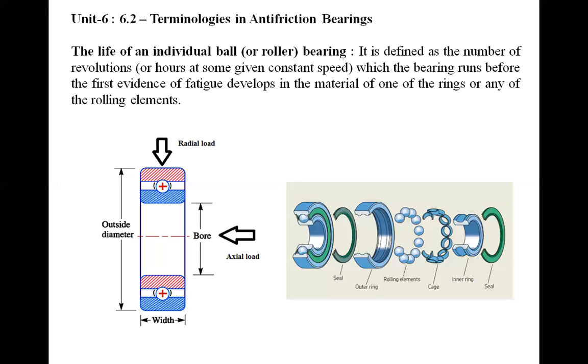That means a compression-release type of loading happens on the ball or roller. Because of such repeated loading on any component, it is subjected to cracks, and that property we call the fatigue property.